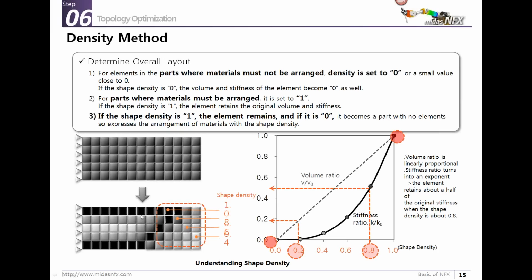But during the optimization process, in function of the boundary condition, the loads, and all the constraints that you defined, the optimization will assign some kind of coefficient to the mesh. So it will say this mesh is necessary in my analysis, so it will stay equal to 1 for the mesh density ratio. But in some area, I don't really need to have this mesh in my analysis, so in this case, it will be set to 0.